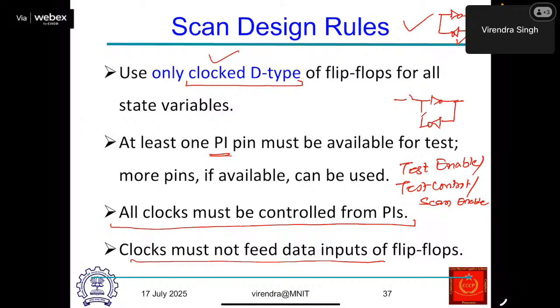But when I have this scan infrastructure on the circuit, it provides me some additional benefit, that is for the debug. Anytime I can scan in, stop my chip, and then take out all the contents of all the flip flops at the primary output. That helps me in debugging my system, to see what went wrong if something goes wrong.